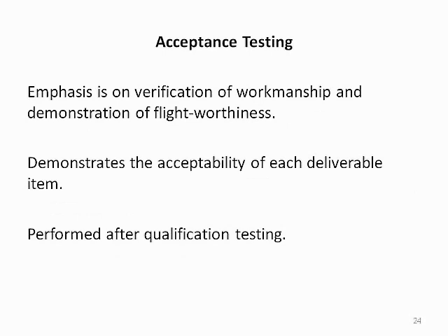In acceptance testing, emphasis is placed on verification of workmanship and demonstration of flight worthiness, not the hardware design. Acceptance testing demonstrates the acceptability of each deliverable item and is performed on the flight hardware after qualification testing has been successfully completed.